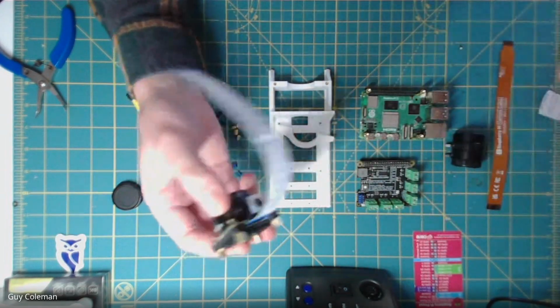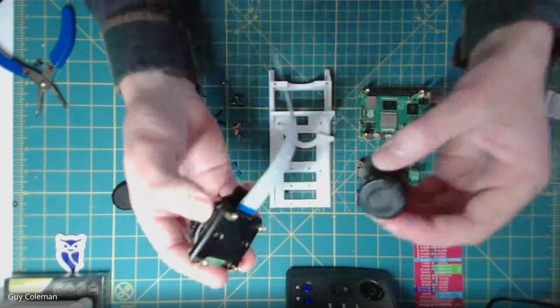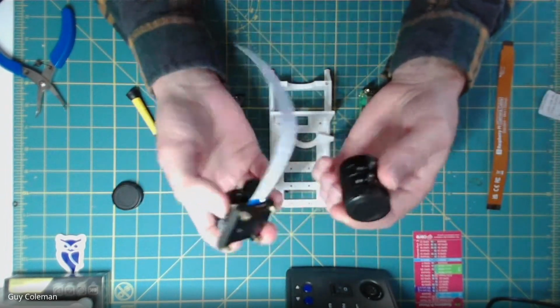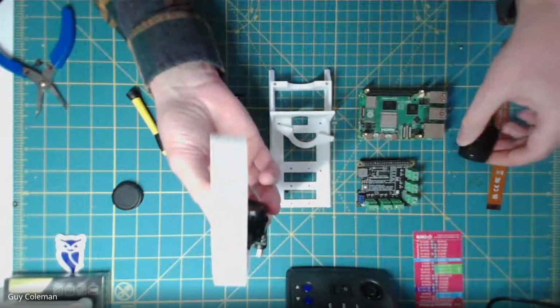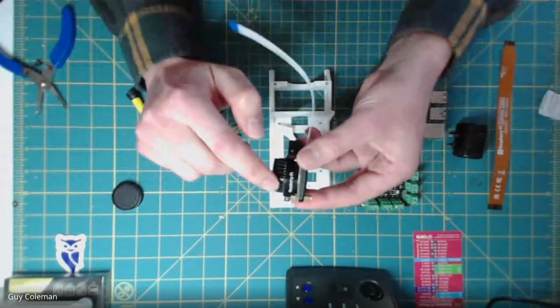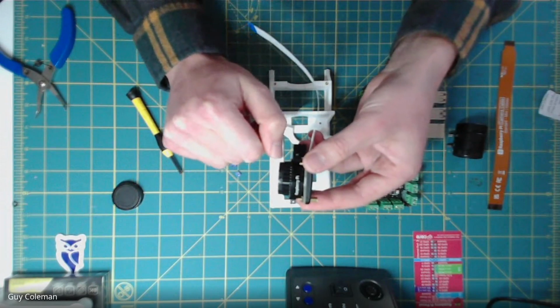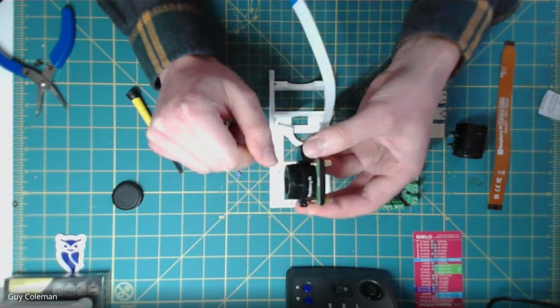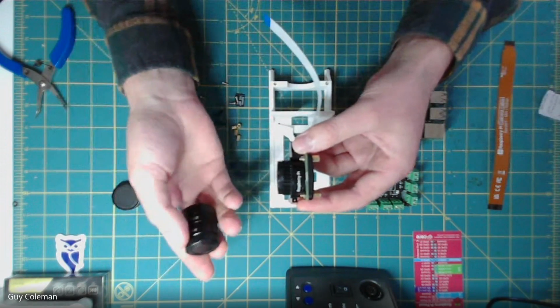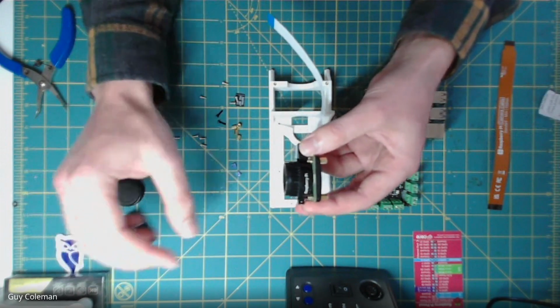So I guess the first thing I do usually is sort the camera out. This is straight out of the box. This is how it comes. There's a few different things you need to remove from here. The first is this adapter ring. I know this always got me the first time I did it, and that adapter ring will mean you can never actually focus the camera with this lens. So it's a C to CS mount adapter, which you don't need.